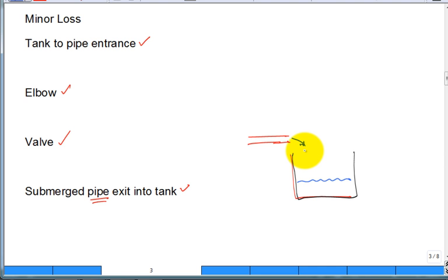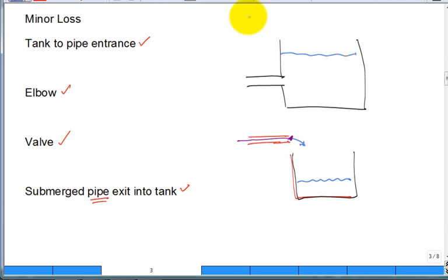Yes, sir. Is it just because of the density of air relative to the... No, it's because you end your Bernoulli line right there. And because you end it there, the exit speed is not negligible. But if you have the other case where you have the pipe into a tank and the outlet of the pipe is submerged, you don't end your Bernoulli here, you extend it all the way to there. What is the speed at that point?